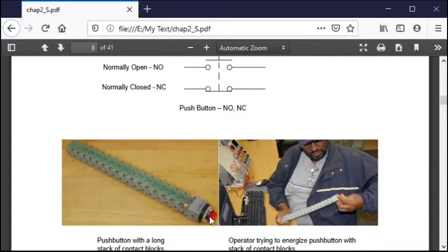If you use a programmable controller, you just run the first signal from the first contact into the programmable controller, and you can use it as many times as you want to, for as many pieces of logic as you want to. However, if you were designing with a schematic and didn't have a programmable controller and you needed this many functions, you would have to put that many in there. You say, I would never do that.